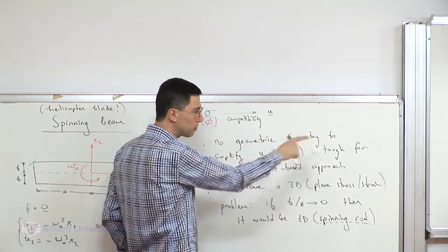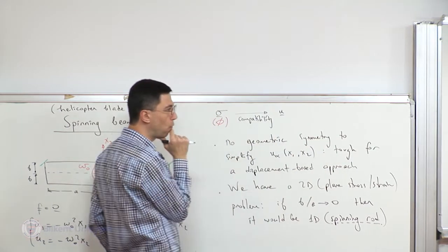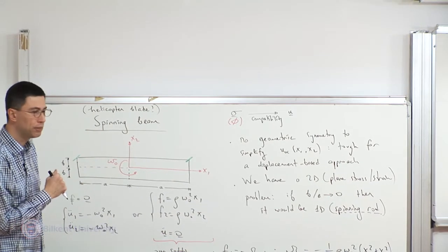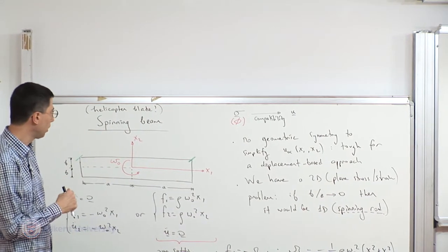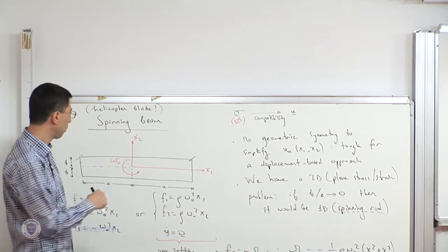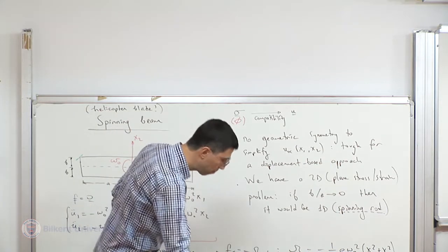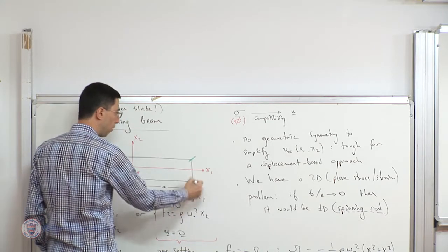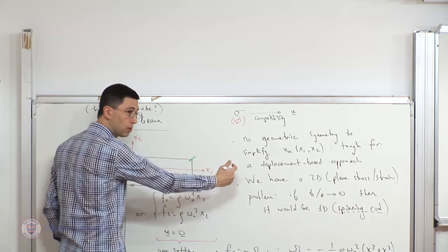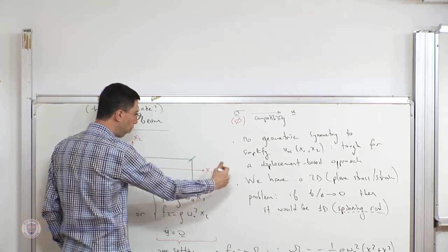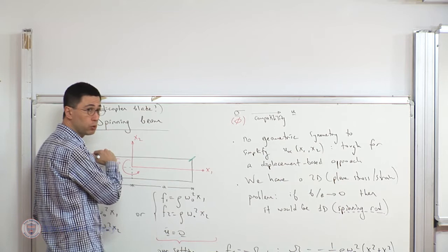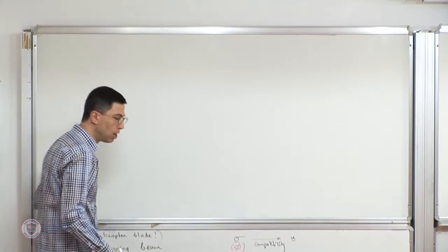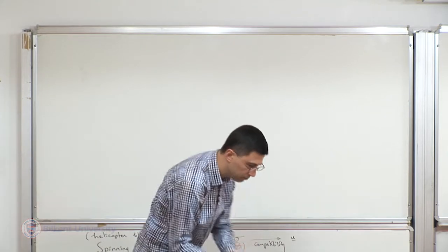But it turns out that sometimes it is better to simplify that form a little bit by first looking at the boundary conditions, because I know what the stresses are at these functionally. So I can say something about those constants by looking at the boundary conditions. And the boundary conditions are, for instance, at this point, sigma 2,2 is equal to 0. Along this line, sigma 1,1 is equal to 0, okay? And also, both here and there, sigma 1,2 is also equal to 0 because they are all traction-free boundary conditions, okay? So I'm going to make use of that first.